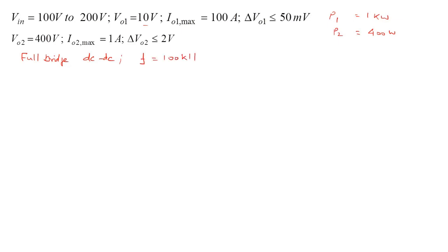A design with 200 kilohertz or 50 kilohertz is certainly acceptable, and so is a forward converter design, as long as, as I said earlier, it meets the switch voltage requirement. Flyback will rarely be used at kilowatt power level, so it's best not to consider a flyback for this application.